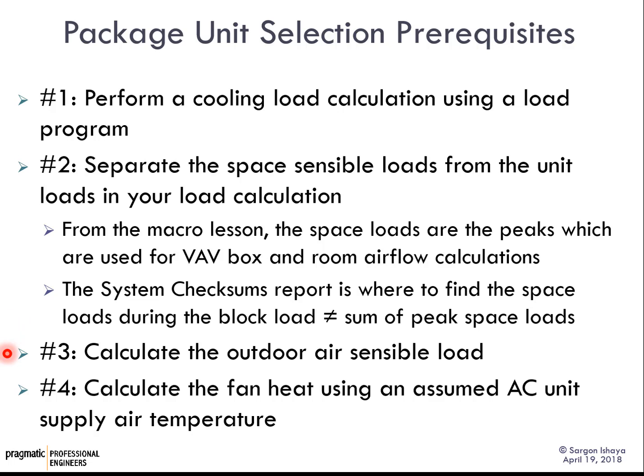You need to calculate the outdoor air sensible load. Now, I haven't shown you how to do that yet, but that needs to be done before you jump into selecting a package unit. So we're going to go over that. And you also need to calculate the fan heat. Again, that's not something that you've done yet, and we're going to review how to do that, but it has to be done before you, again, select a package unit.